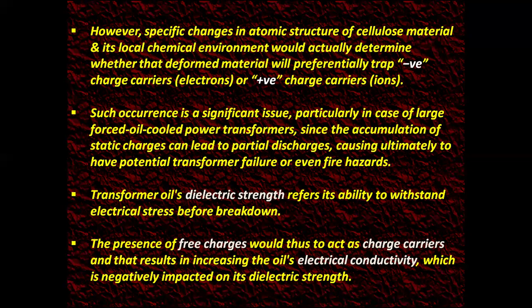Such occurrence is a significant issue, particularly in the case of large forced cooled power transformers, since the accumulation of static charges can lead to partial discharges, ultimately causing potential transformer failure or even fire hazards.